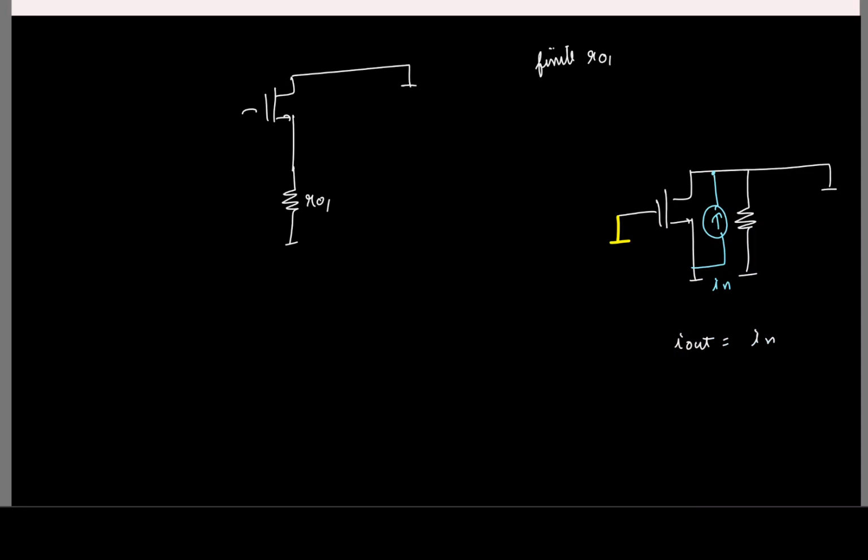Now this, let me finish it. So the second thing is to find the transfer function from the input to the output. Even if you have an R0, if I short this, if this is VN in, this current is GM VN in, and that current will entirely flow into the short circuit. So even if you have R0, it doesn't matter. The input referred noise voltage for a MOSFET will have a power spectral density 4 kT gamma by GM. Even if you have R0, it doesn't change.